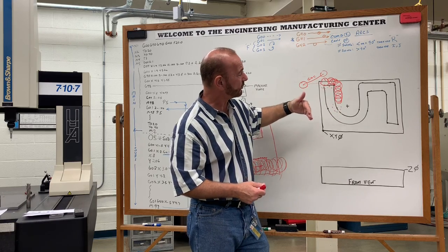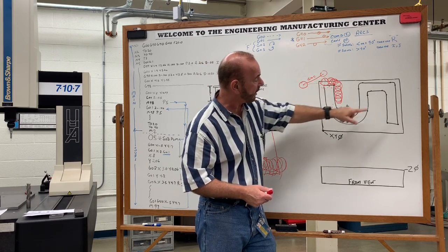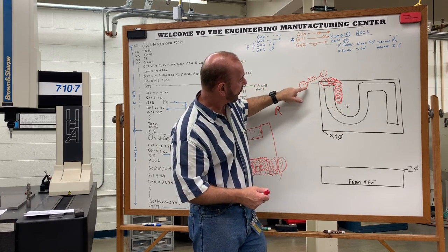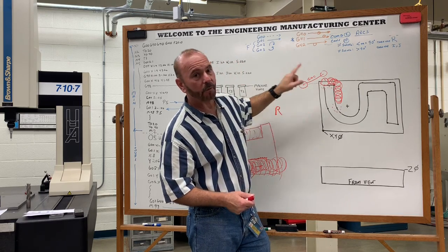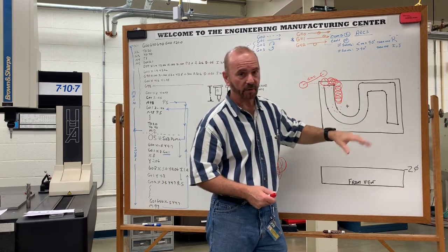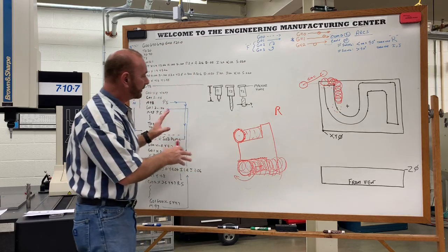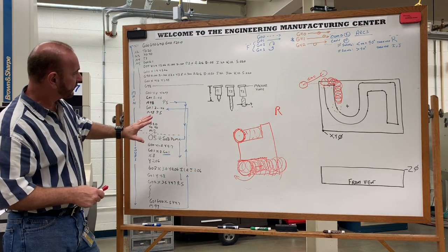So it's just good general practice that when you turn cutter compensation on, turn it off with a ramp on move before raising the cutter up and moving it to another part of the part. So that's basically the whole G-code scenario.